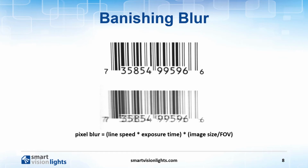The best image quality will limit pixel blur to 1 pixel or less, although this level of performance is not always necessary. High-speed inspection applications often specify the allowable threshold for pixel blur, and vision engineers design systems accordingly. Traditionally, engineers use the following formula to calculate the minimum exposure time required to avoid a specified pixel blur. Pixel blur equals line speed times exposure time times the image size in pixels divided by the field of view.